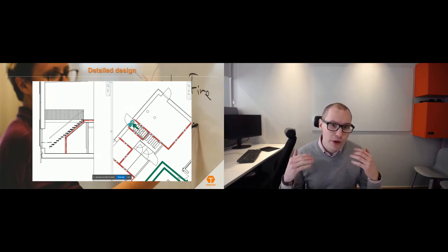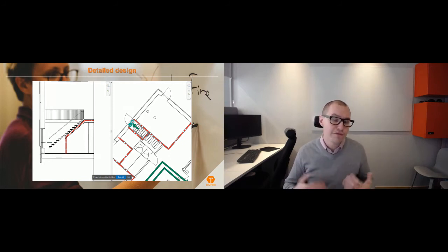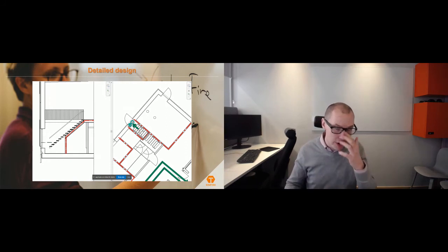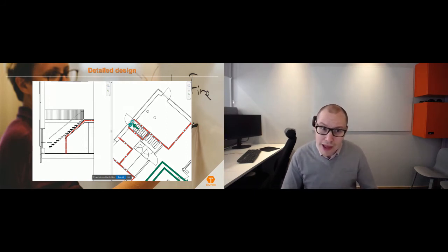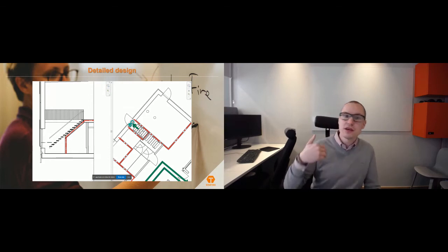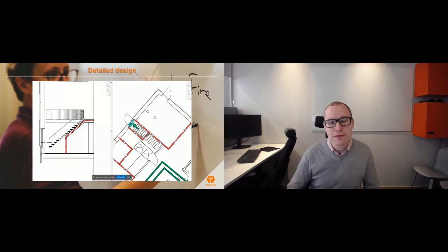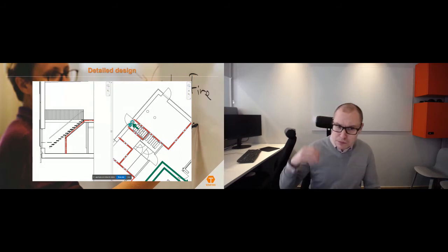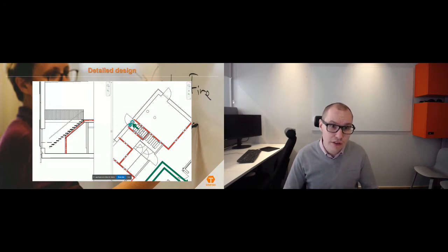The thing is, here you want the fire compartmentation under the staircase. And as a fire engineer, what we print or have as PDFs is mostly floor plans. Of course, there are some critical sections that are delivered as well from the other stakeholders that we can use. But this staircase would not be one of those critical sections for sure. So you would have your fire documentation telling the architect and the construction engineer, you need to have some fire resistance on the staircase in this room. Tell us when you've done it.